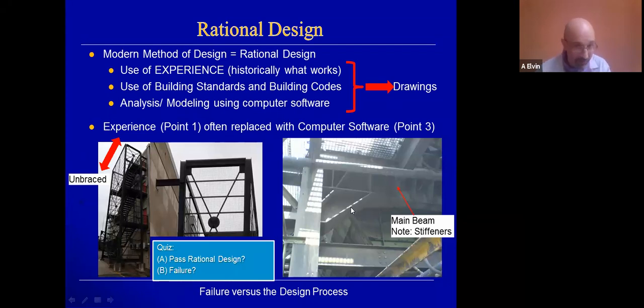Has this one failed? This structure, has it failed? Yes, it's failed. Anybody else? No, it has not failed. Stiffeners not following standard design, therefore failed. Haunch too weak, axis of column. Ah, that's very good. Cool. Yes, it failed.